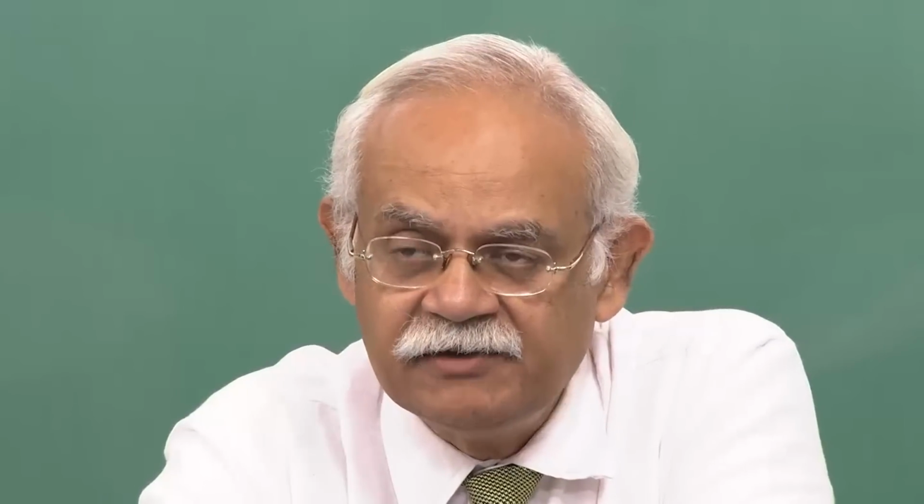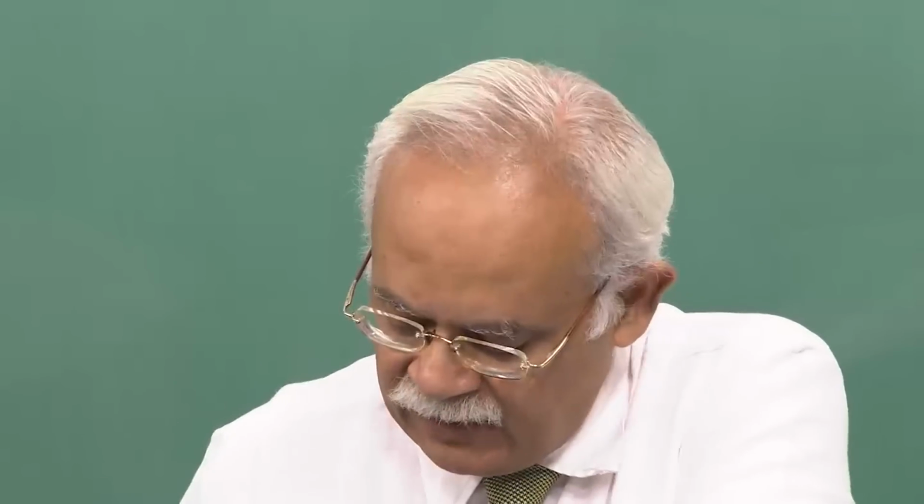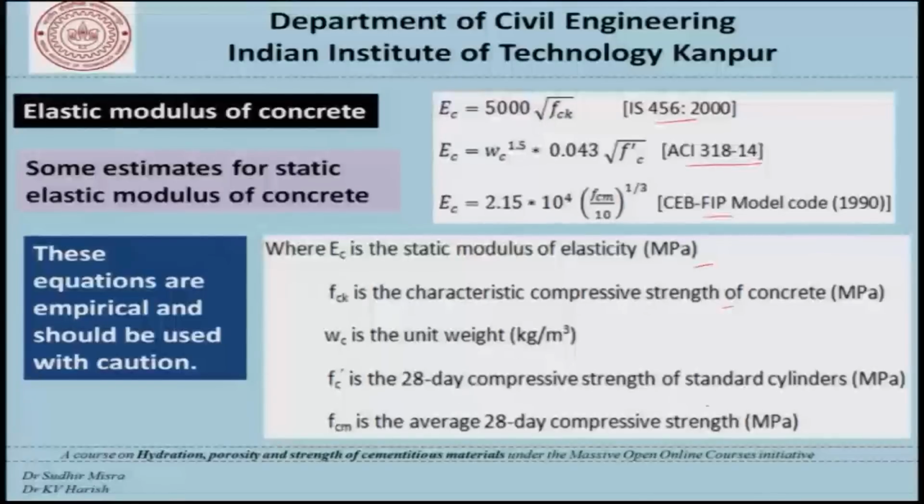So the designers have to make their choice, and that is very important to appreciate that even though the code allows you to use these equations to estimate the modulus of elasticity and perhaps so many other parameters, we must make a judgment that indeed the estimation is within the range which was foreseen by the people who wrote that document. So having said that, we should remember that these equations are largely empirical and should be used with caution.